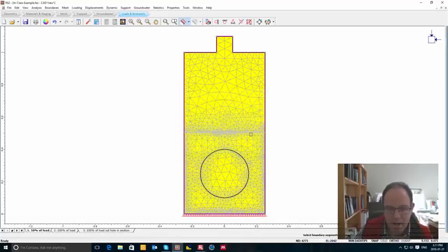We push OK. And now the next boundary line that we click on, that stress is going to be applied to it. So we're going to click on this top tab, and then we're just going to push Enter. And you can see there, it was a 10 MPa stress, and we applied it in 50% in stage 1 and 100% in stage 2, acting vertically upwards.